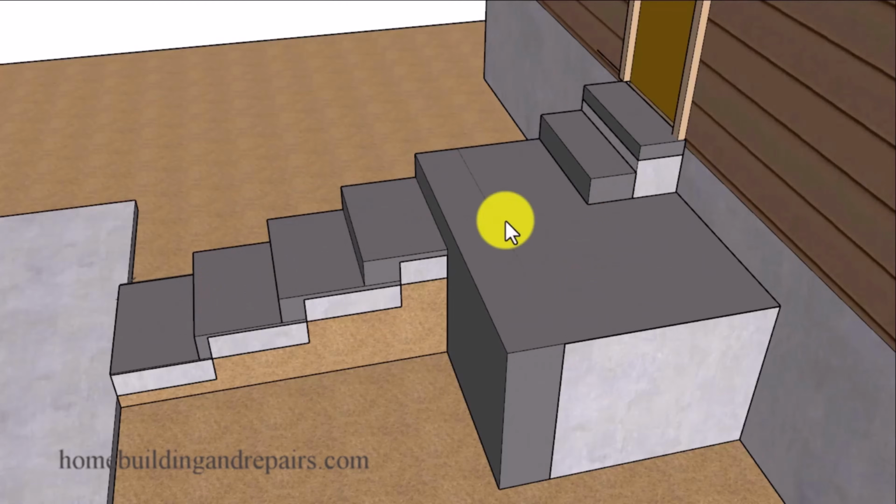Or we can redesign the stairway again. Make the steps smaller here so that we can extend the length of the deck out another foot to give us the desired measurement we need here, so that it could be approved by local building codes. However, you would need to verify with your local building department as to whether or not they're going to consider this a separate stairway from this one and allow you to use different size tread depths or riser heights.